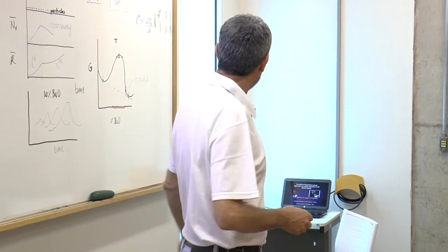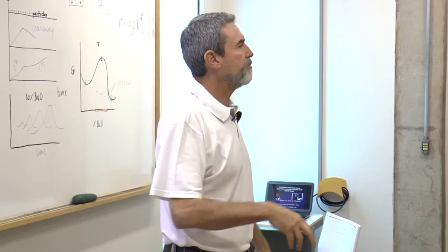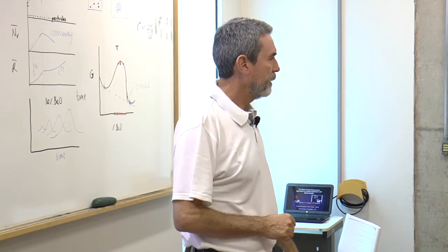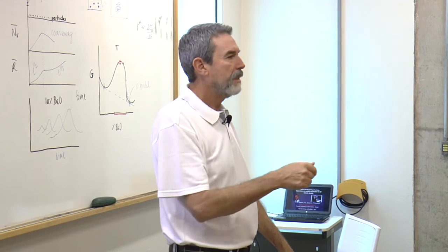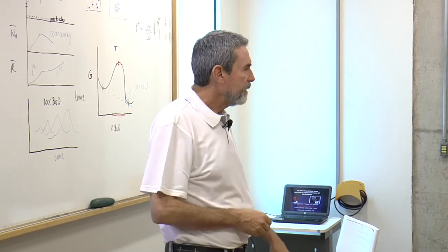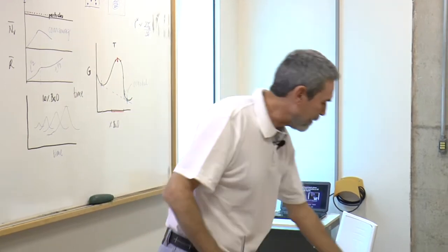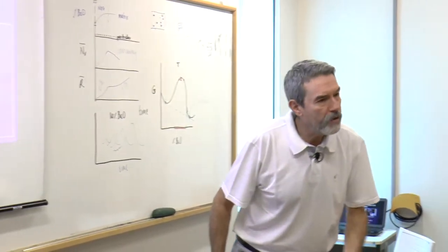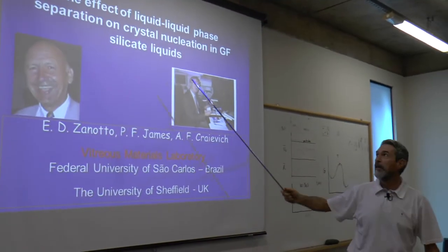The typical critical size to form a crystal inside the glass matrix is about 10 angstroms or so at TG. And 10 angstrom, you can imagine a cube of 10 by 10 by 10 angstrom. That means 100 atoms, 150 atoms or so. I'll give you a surprise next class about crystal nucleation. Anyway, this is like an introduction to nucleation because you have an idea now about liquid phase separation.